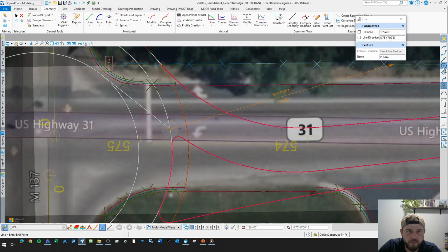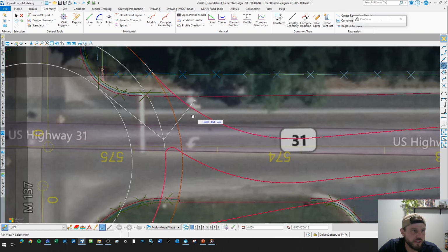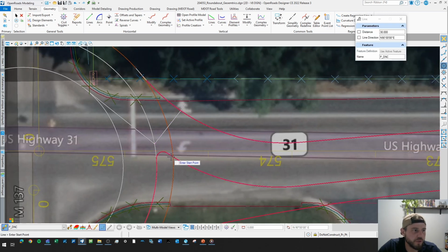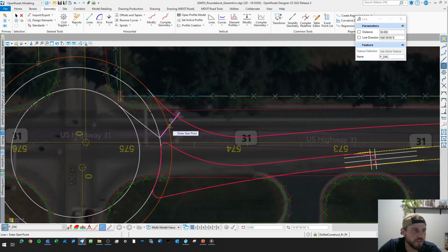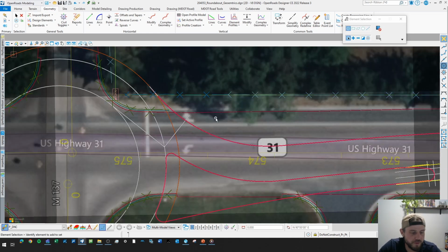Then from there, I'm going to select the center circle snap and point back to this radius, but give it an exact 30 feet and click, and it should go 30 feet directly perpendicular from this intersection at this point. So this is my entry. This is what I'm going to decide my entry width is.